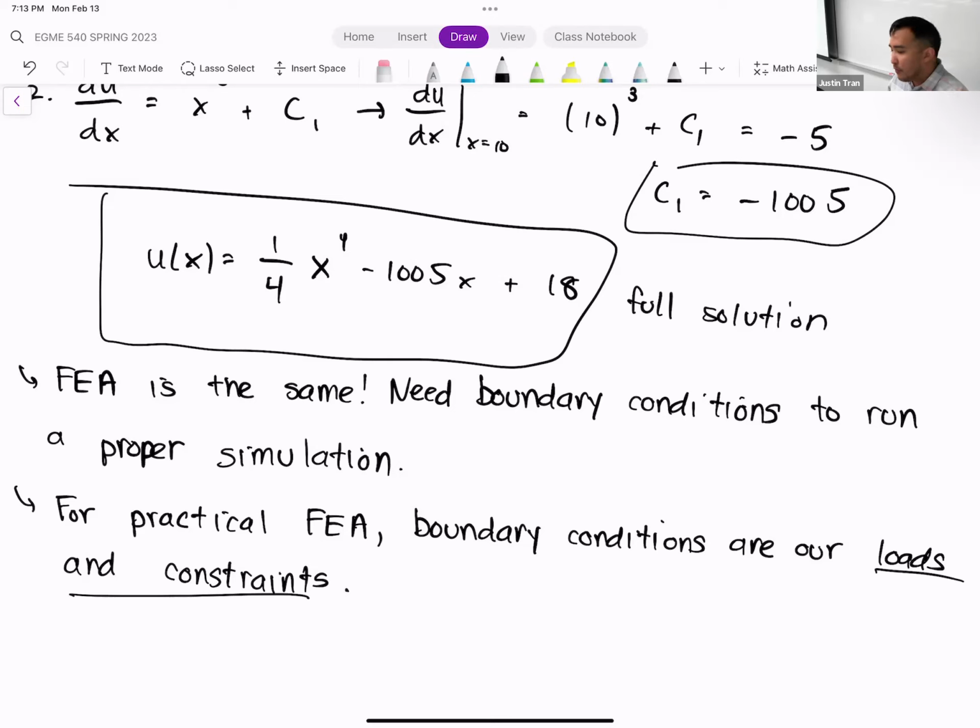For instance, the very simplest one you can think of is, let's say you're applying your load as a force. That's what we did in activity 2. You apply, like, a 100-pound force in a certain direction. You can obtain the same results if you change that force to a pressure load instead. If you compute the pressure such that it applies the exact same amount of load as the force, you get the exact same result. Exactly. Thank you, sir.